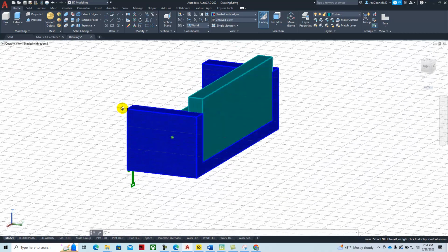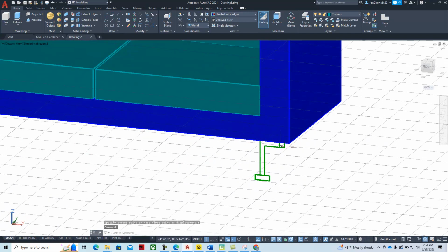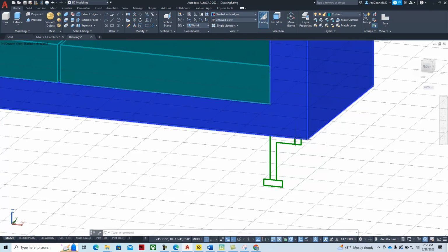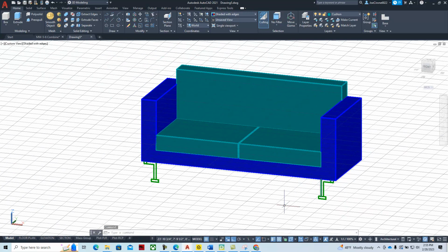We can start to add the base of it. And so as we look at these components right here for the frame, what we can do is we can extrude this 30 inches and maybe we'll take it back 29 inches. And so we can press pull this. And if you can't get it, then just put another rectangle on it. And so we're in the XY axis, and so that's what the problem is that when I 3D rotated it, we're always working in the XY axis, so we need to update that or use a dynamic UCS.